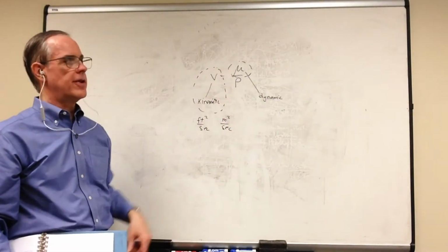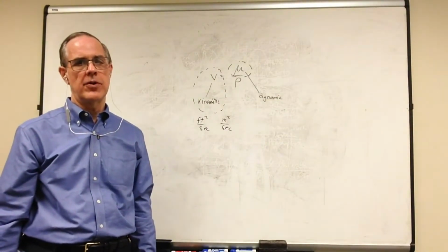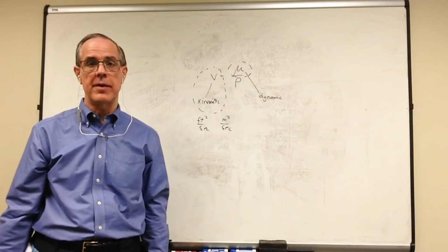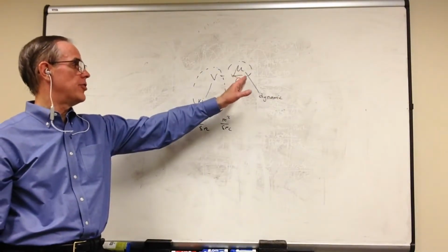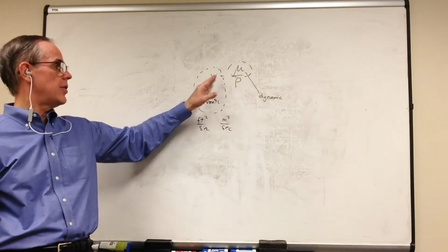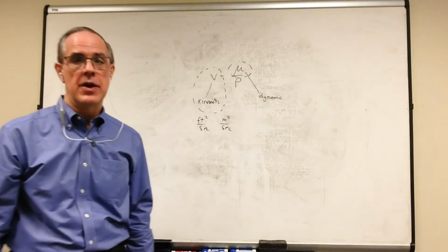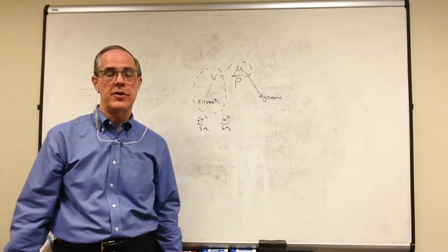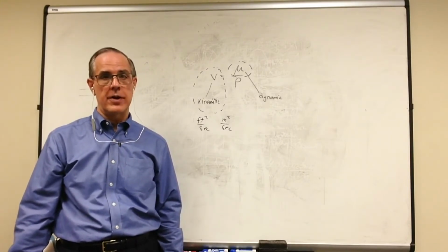With mu you always get messed up with g sub c, particularly in the US system of units. So I would strongly recommend that, obviously mu is what the machine will measure, but I would suggest you use nu values for future experiments. We'll see this when we get into the later experiments such as flow metering, and certainly we'll get into it with the wind tunnel.